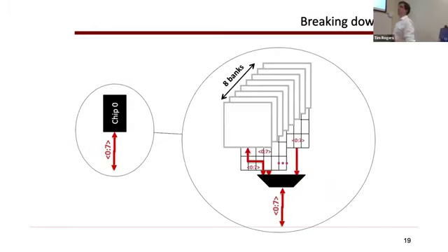And then inside of a chip, there's actually multiple banks because it takes some time to read things out from each individual bank. And we want to have a bunch of storage inside each chip. And we can't just make it bigger, right? If we want more storage inside the chip, we can't just make these rectangles larger. So we add more rectangles, and that increases the capacity. And it also gives us an ability to overlap the accesses. So you can initiate a row address strobe to one bank. And then while that's processing, you can initiate another row address strobe to another bank, for example, and start overlapping their reads or their writes, so that way you don't waste time.